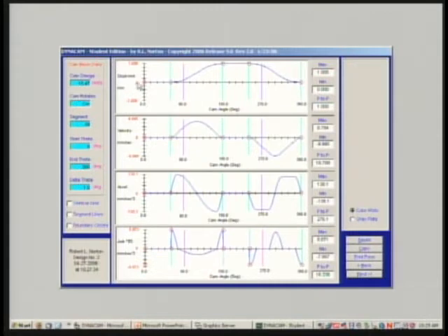and we've asked for the SVAJ, which is all we have available at the moment. And now we see the whole interval from 0 to 360. And you can see the dwell at 0, followed by a rise to the 1 inch, in this case, dwelling at 1 for 60 degrees, falling back the 1 inch over the last 120. The circles drawn here can be turned on and off with a switch down here. I suggest you probably want to leave them on because they're going to show you whether you have a problem.